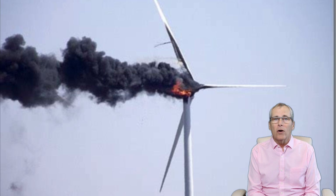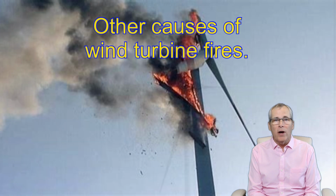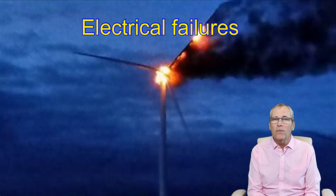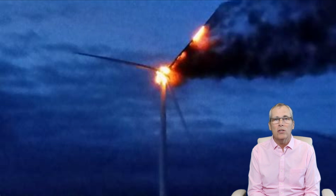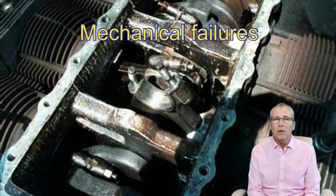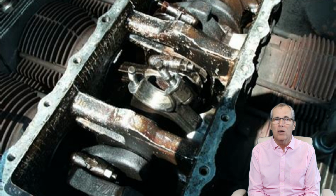There are several other causes of wind turbine fires beyond obstructed air filters due to unanticipated dust conditions. Some of the other common causes include electrical failures. Electrical failures such as short circuits in equipment malfunctions can cause overheating and can lead to fire. Mechanical failures such as gearbox or bearing failures can also lead to overheating and lead to a fire.